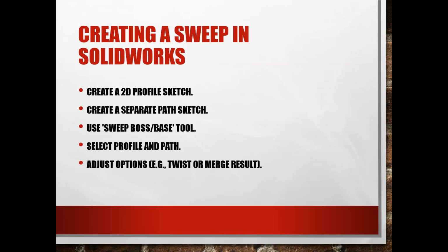When we're talking about sweeps in SolidWorks, remember, we're going to do the exact same thing, and all of these are going to work exactly the same. We're going to create some kind of profile. We're going to create some kind of path. And in here, the tool that we're going to be using is going to be called the Swept Boss/Base.